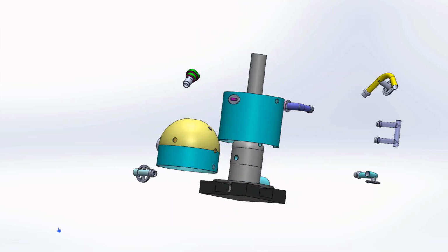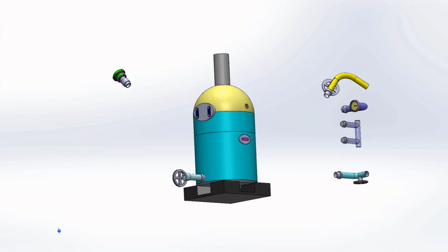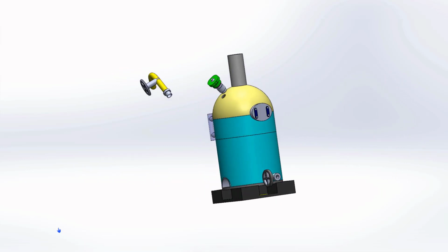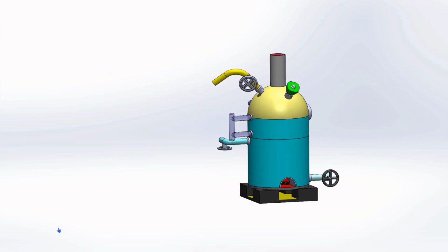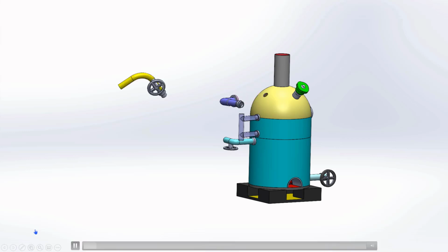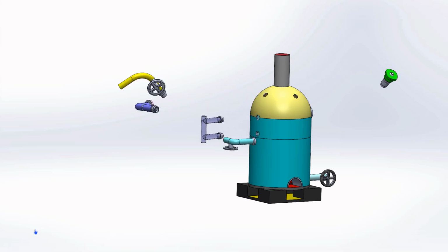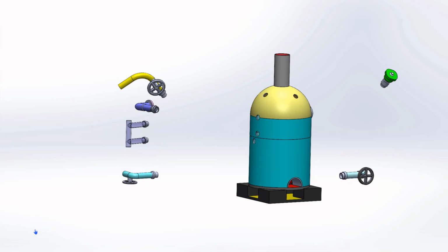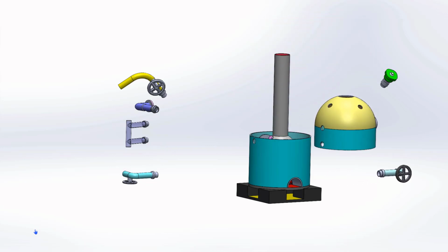The safety of the boiler is very important because the boiler works at high pressure and handles high pressure steam and water. If the boiler explodes due to high pressure or absence of water inside, it is a catastrophic failure of the boiler and it may cause many damages. There are many devices attached to the boiler to ensure its safe operation, and the set of such attachments are called boiler mountings.